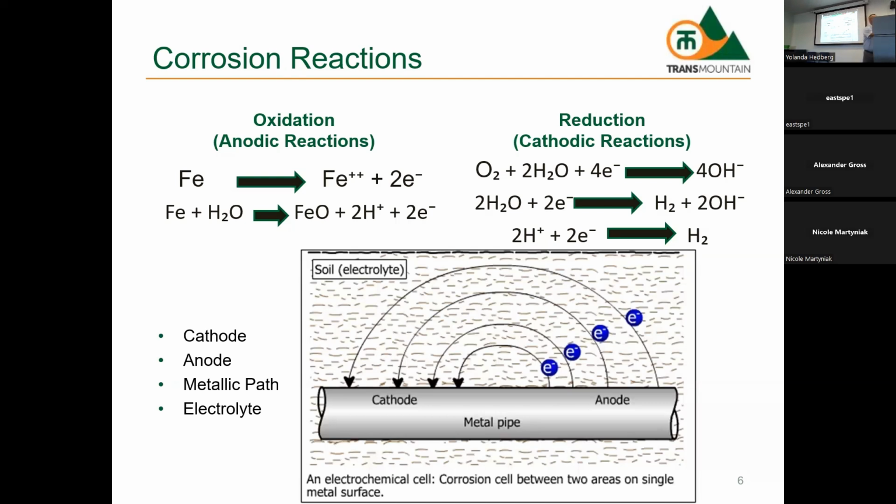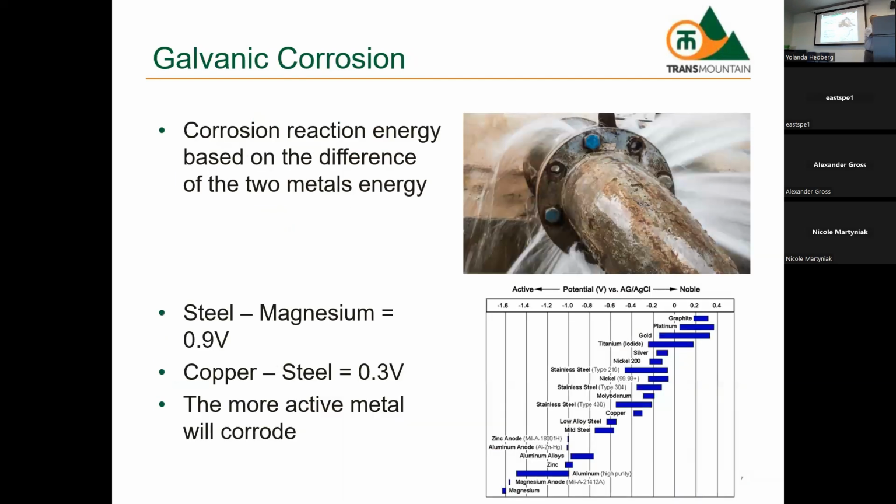I'm done, Ed. Or maybe one more slide, and then we'll get into some more detailed stuff here. Talking about galvanic corrosion, again, it's that coupling of the two. You'll see this a lot with rivets, bolts, different metals that are touching. And you want to actually isolate in between the two to eliminate that.